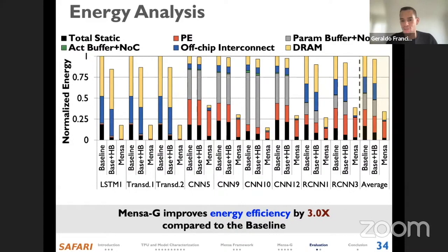and overall that would add up to the total energy of the system. So it would not be ideal. It's really important to try to minimize the number of accelerators as much as possible when tailored for energy. In terms of throughput, maybe the throughput will be higher because you have just more processing element arrays in the end, right, or more hardware itself. But in terms of energy, edge devices are quite power sensitive, so it's really important to keep it down as much as possible and have a slim system, so we are not killed by the static energy of hardware sitting doing nothing.